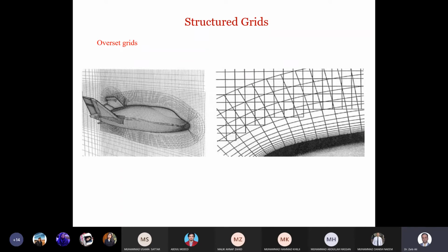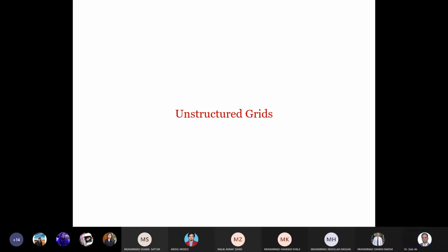As you can see, interpolation will be an additional computational overhead. And accuracy is also sometimes compromised. So to avoid the shortcomings of structured meshes in handling complex geometries, nowadays the major push is towards unstructured grids. And of course, the main advantage is the ability to handle varying mesh shapes and varying body shapes and sizes.